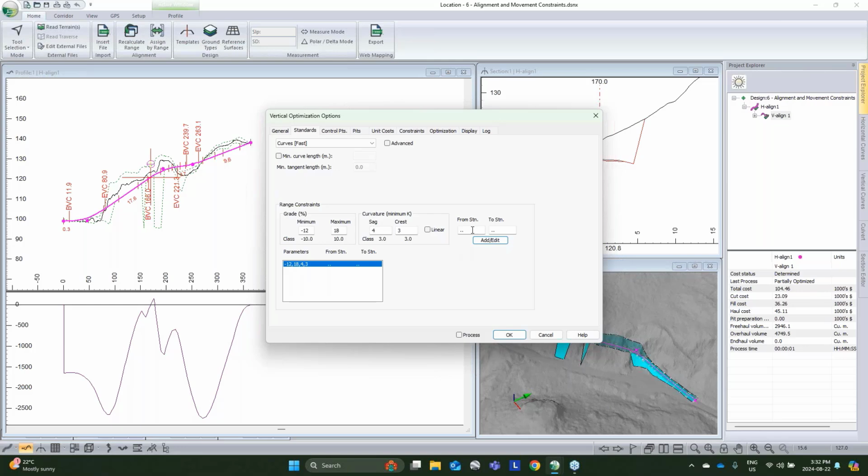This one's not really set up to be a good example for that, but as Erin said, wind farms, this is a super common parameter to use. If you have steep roads to get to your turbine sites, you can account for that. But as your road goes through an actual pad, you can reduce those grade constraints through the pad. You can even tell it to be a linear section, so on a vertical tangent, and you can do that by station X to station Y.